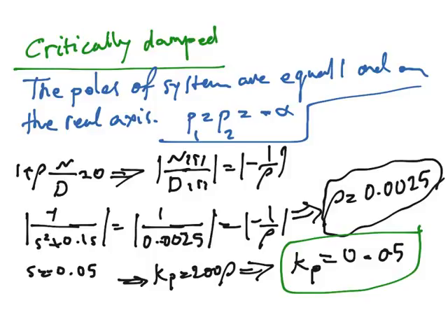What's the next question? Here we need to find the steady state error E infinity to the input of ramp, phi ramp t, for the same closed loop system. So for the same closed loop system means that Kp will be equal to this value that we have obtained, and then we need to determine the steady state value for R. Now the Ls that we have can be expressed in this format.